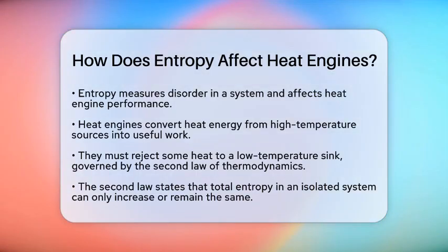Let's break this down. Heat engines take heat energy from a high-temperature source and convert it into useful work. However, they also have to reject some heat to a low-temperature sink. This process is governed by the second law of thermodynamics, which tells us that the total entropy of an isolated system can never decrease. It can only increase or stay the same in ideal situations. This principle sets limits on how well heat engines can perform.